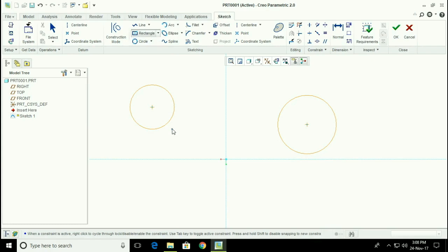To draw a 3 point circle, the circumference of the circle or the center point of the circle must be intersecting with the other points or surface of any object, like a rectangle. We draw a rectangle here. Okay. Now for the 3 point circle, that's 1 point, then the other, and for the third point, the center point of the circle interlinked with the diagonal of the rectangle, and that makes the third point of the circle.